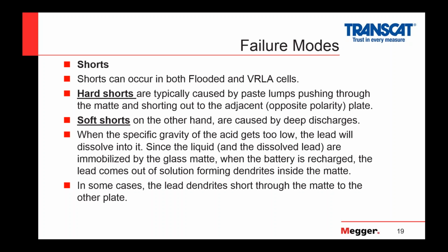Now, car batteries, like I said before, when they get over discharged, these are batteries that have a tremendous amount of surface area, a lot of plates and very thin separators in them. They're very thin because they're trying to maximize that surface area. So when the voltage goes too low in them, the lead gets trapped in that separator and will short those plates out. So when you go to recharge it, you still have those shorts in there. You have a whole bunch of micro shorts in the battery.